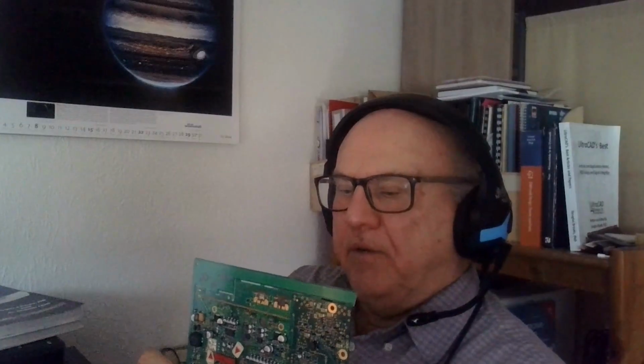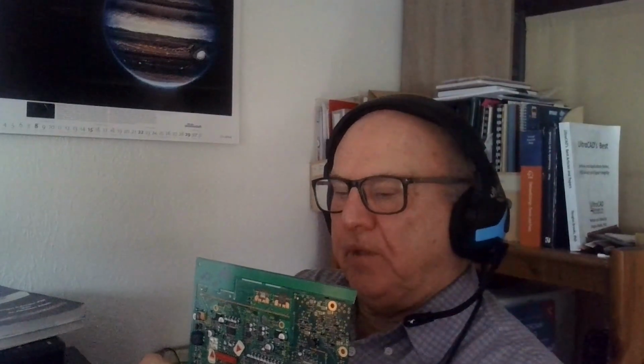In civil airplanes, this technique is called wedge lock cooling. I see. And that's my experience from a couple of consulting projects, that it's almost impossible to bring heat from the center to the periphery. But in an airplane, we always have ventilated cabinets where the heat is then taken by the airflow.